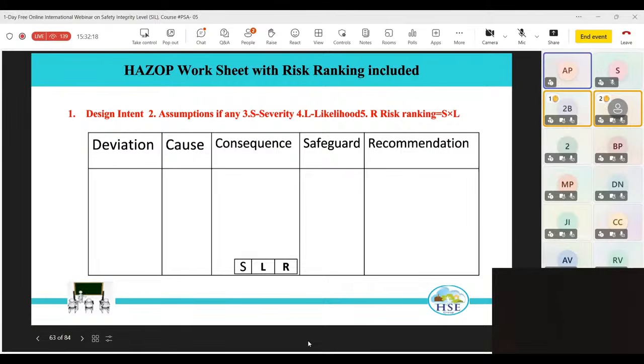So out of that safety wall, we cannot take credit because we do not know whether whatever is coming out of the ruptured vessel is left to open atmosphere or goes to a closed circuit. That's why we have to consider that the only safeguard available to us is this SDV and PSH2. And in that case, if we want to ensure that it functions when it is required, then we would recommend